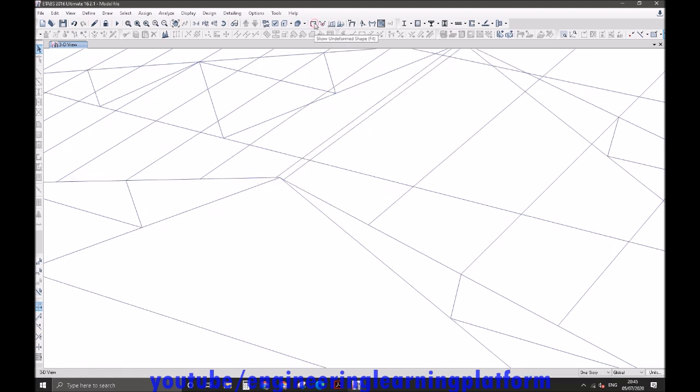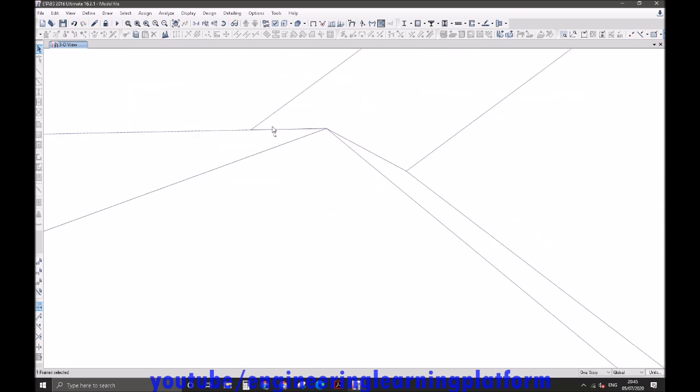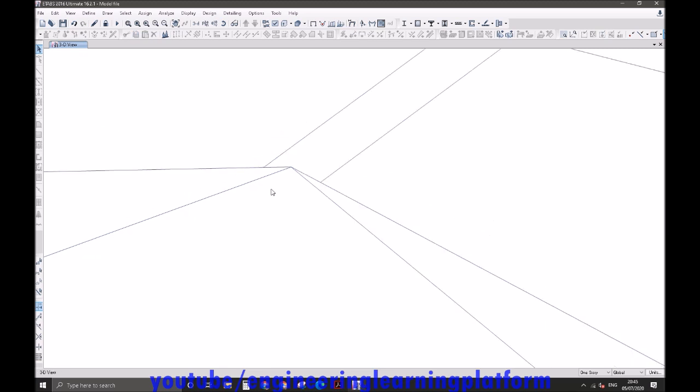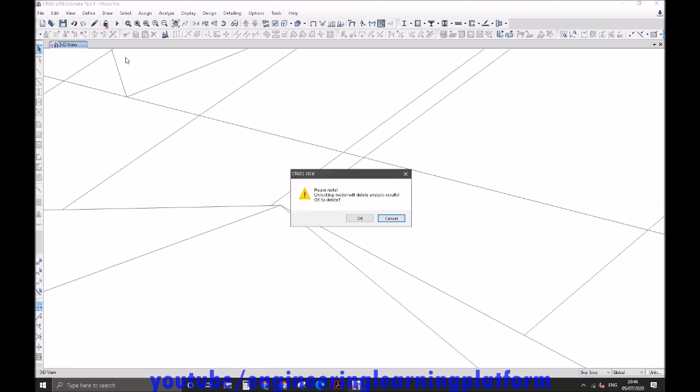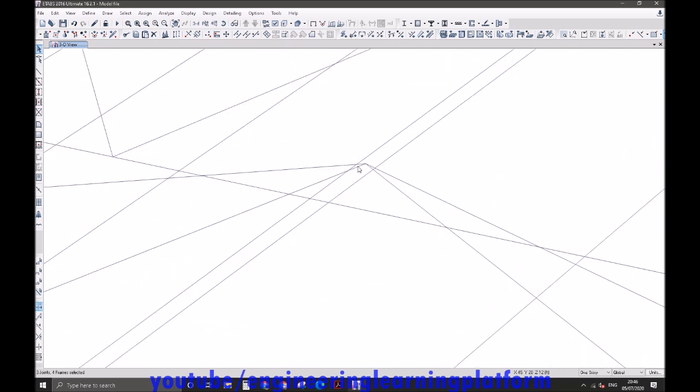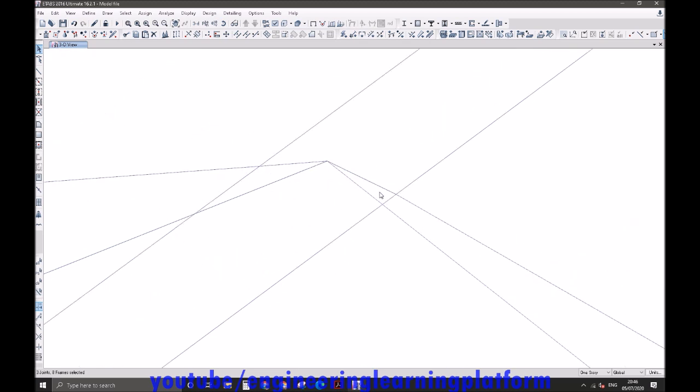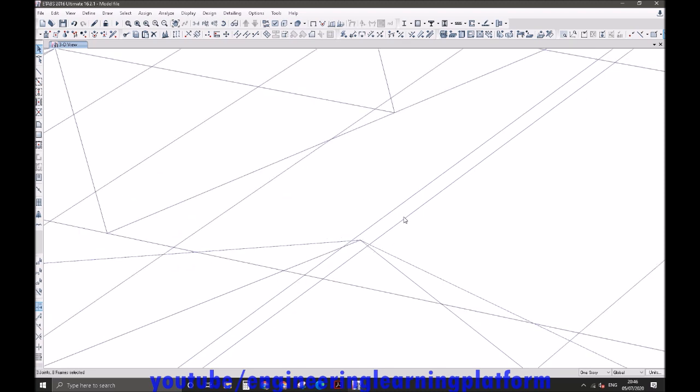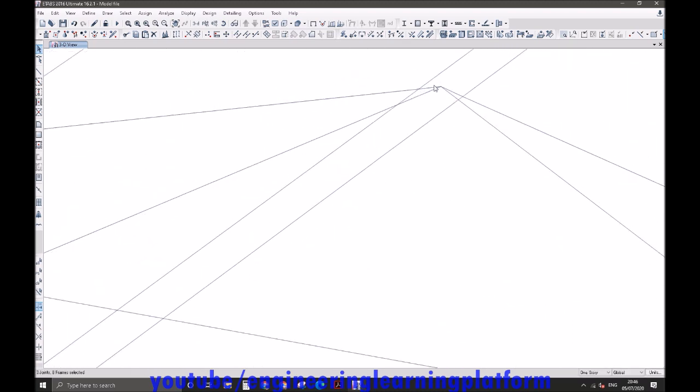You can see that the top chord is not properly connected to the ridge point of the truss, as unfortunately I might have missed joining the top chord to the last point, which was taken 3-inch left and 3-inch right in order to do the realistic modeling, to leave space for the flange of the purlin. It's actually not okay.